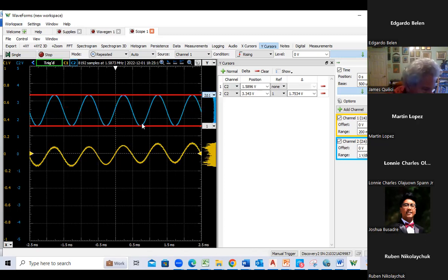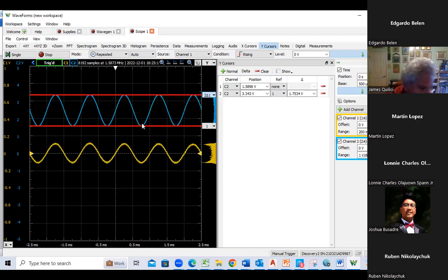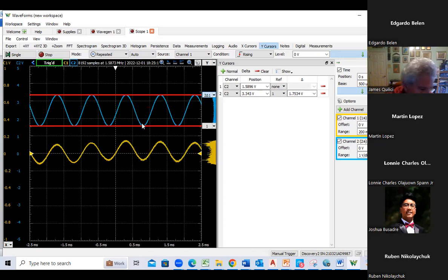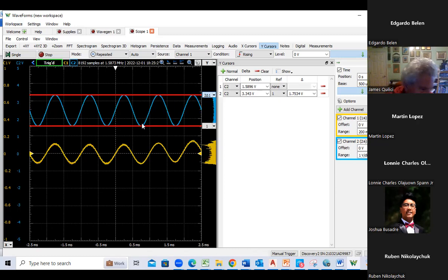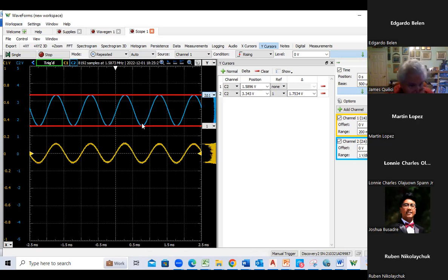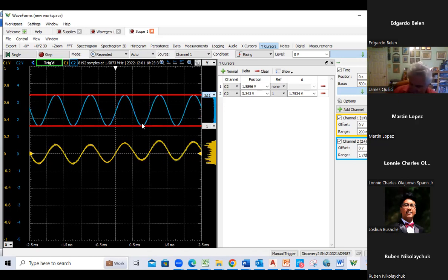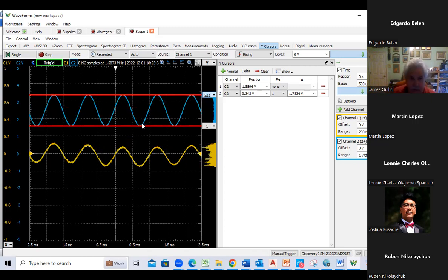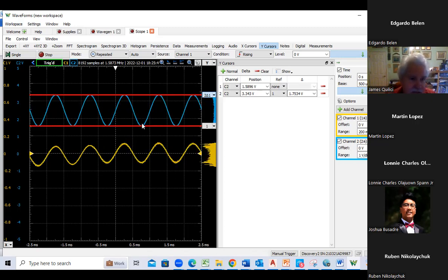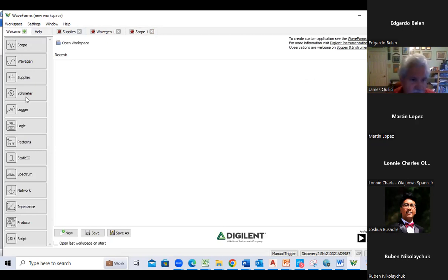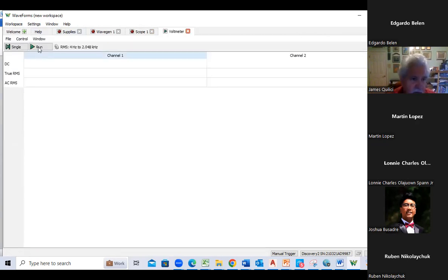Okay. So then step 8 of the testing says check the collector current and bias voltages, and state whether the bias conditions are reasonably close to the design values. So we don't necessarily have to put an ammeter in series. I've got my little handheld voltmeter here. You can use the one in the Analog Discovery too. To do that, actually, let's just do that. Let me think. Scope. I do this. Voltmeter. Run.